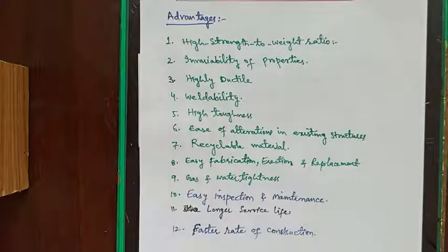It is easy to inspect and easy to maintain. It has longer service life if properly protected, and it is a faster rate of construction, whereas RCC requires installing shutterings, reinforcing bars, casting of concrete, which further requires ample time to fully develop the strength.